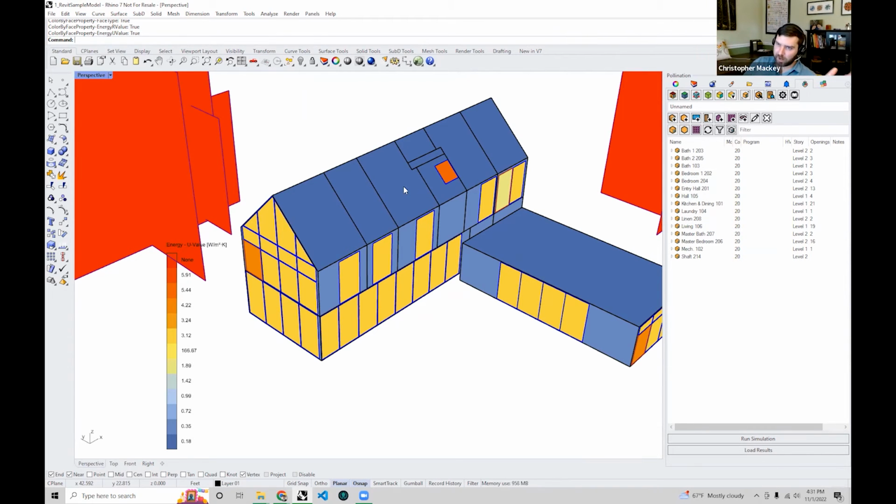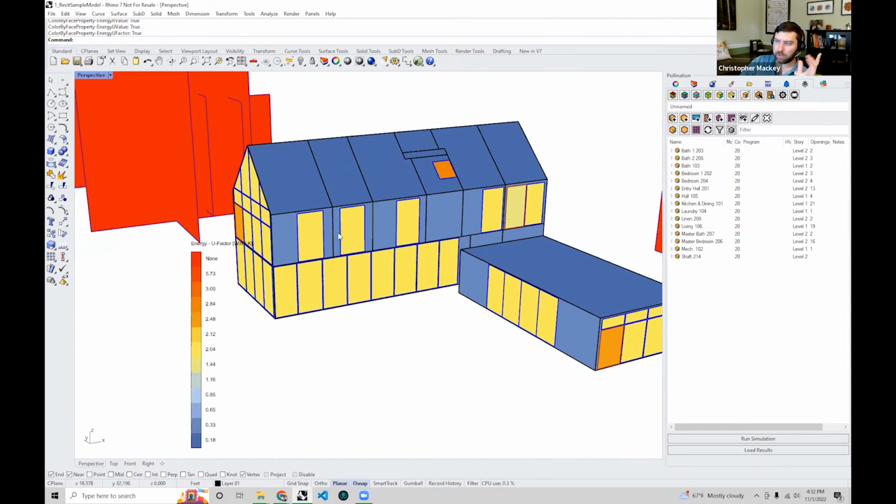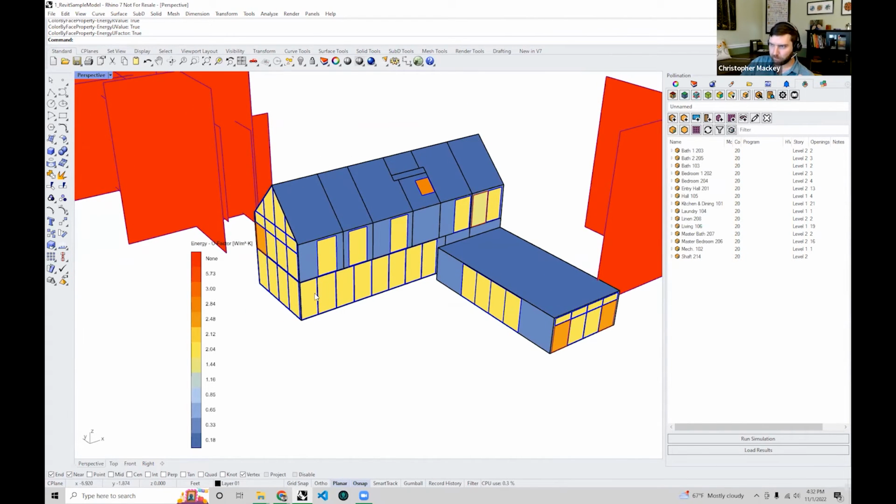More often than not, especially when you're looking at window constructions, manufacturers are going to give you the thermal transmittance with the air films accounted for. So if you want the air films to be accounted for, you can use this U factor. Whenever you see the word factor, either R factor or U factor in our software, that means we're trying to put in air films.